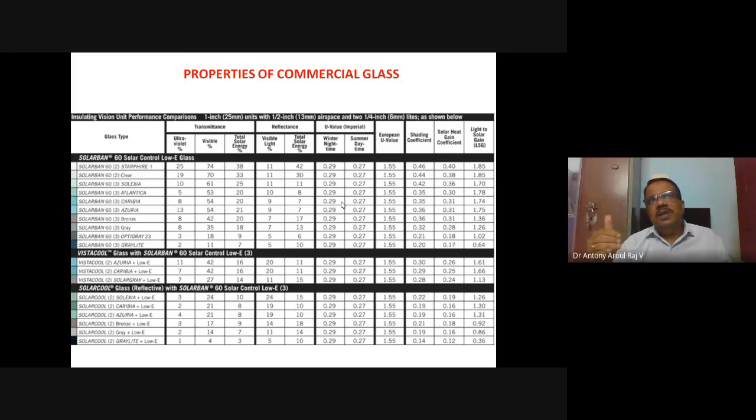So at this point of time, from inside to the outside, transmissivity and other properties will not have a say during night time. Only heat transfer will have a say, because there is no light. Outside it is winter, so inside you will be switching off your light and you will be sleeping. So at that point of time, from inside to outside, or from outside to inside, there will not be any radiation heat transfer. This is very, very important. Your overall heat transfer coefficient becomes important.